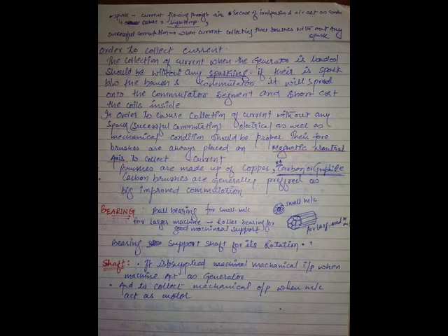What is the pole pitch telling you? We are placing one coil side of a coil in one slot randomly. That is the first slot. When you place one coil side of a coil in one slot, the pole pitch gives you information at which distance the next coil side of that coil should be placed.